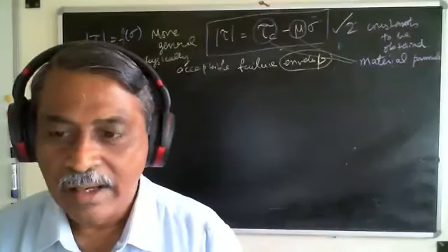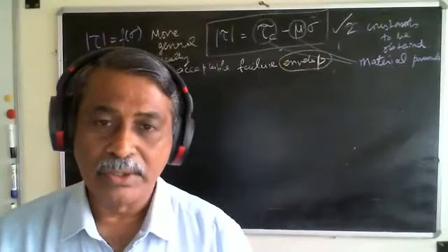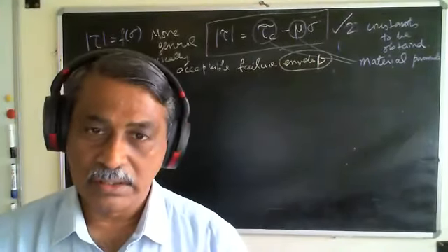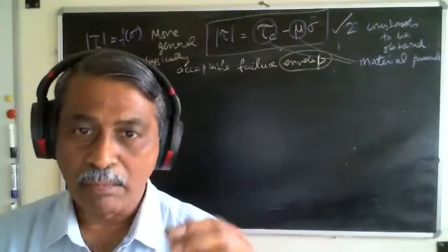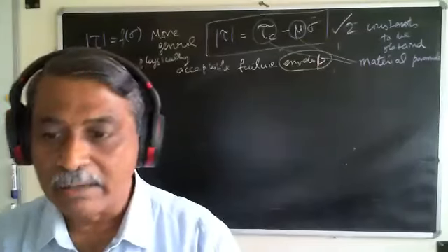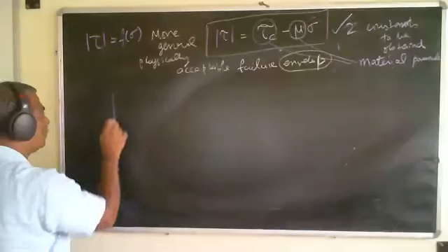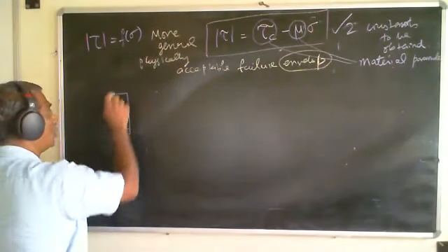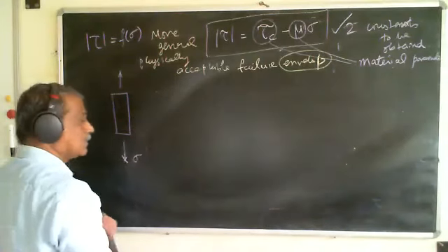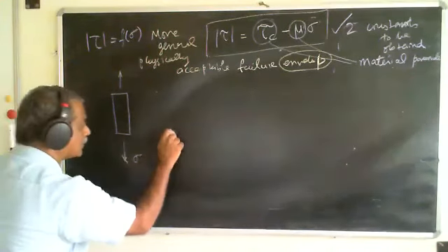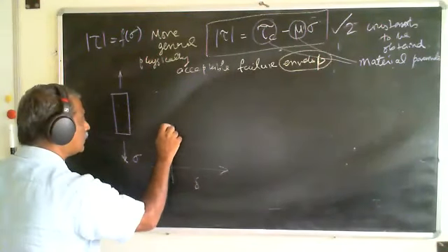Experimenting, right? I have to do a test, right? In the test, what I should do is I should apply a known stress state, right? And find out at what point of that known stress state will it break. For example, if I take, let's say, a simple rod of the material and I pull it, okay? Let's say this is the stress that I'm applying. I keep increasing the stress. So this is, let's say, some deflection and this is stress, okay?